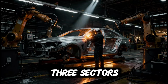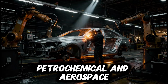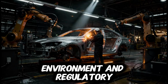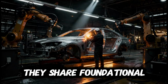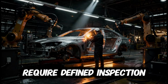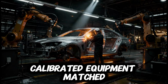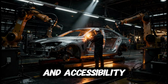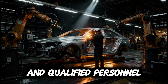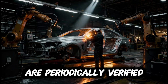So across these three sectors, what remains constant? Although automotive, petrochemical, and aerospace applications differ in scale, environment, and regulatory framework, they share foundational visual testing principles. All three sectors require defined inspection objectives linked to component function and failure modes, calibrated equipment matched to required resolution and accessibility, documented procedures aligned with applicable codes, and qualified personnel whose visual acuity and decision criteria are periodically verified.